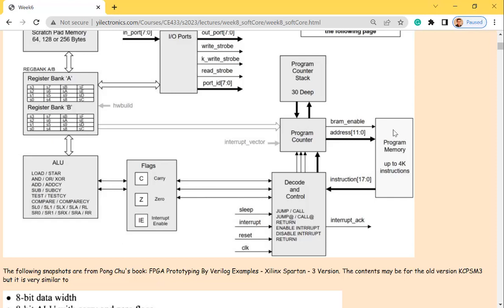But assembly is very difficult for communicating with any I2C devices because you have to write the drivers. Instead, in C, you can directly include the library with the function for I2C, or any other function package, just one line, done. But in assembly, you have to write the driver yourself. You have to deal with all the on and off and all the timing yourself in order to get it done. It takes probably 4 weeks to get just one function done. And so you won't get a chance to work with any real interfaces or sensors at all.